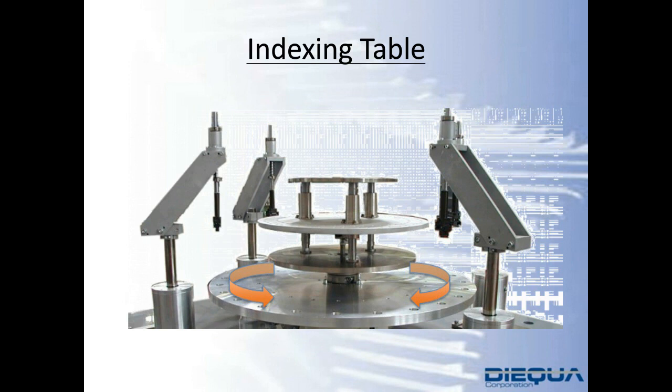An indexing table might seem like the most straightforward reason to have a robot flange. A robot flange literally allows you to bolt the table to the face of the unit. In many cases, the indexing is occurring on a horizontal plane, but you might also experience it on a vertical plane, in which case the tilting capacity will present itself in a radial manner.